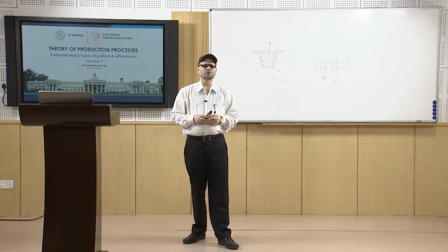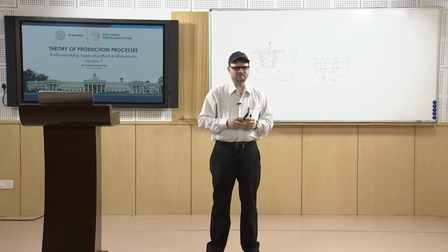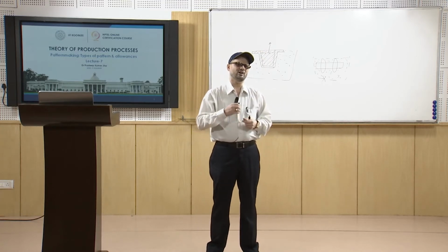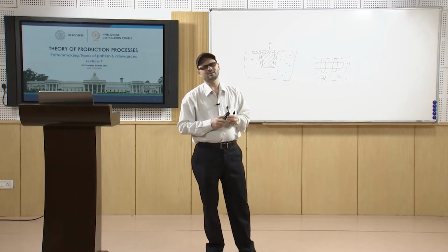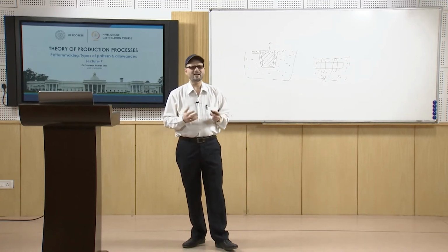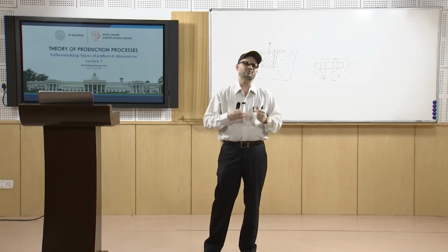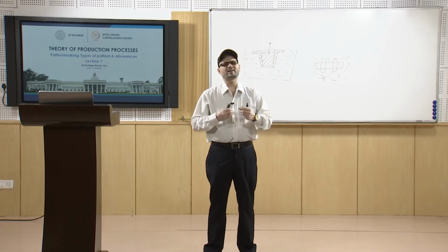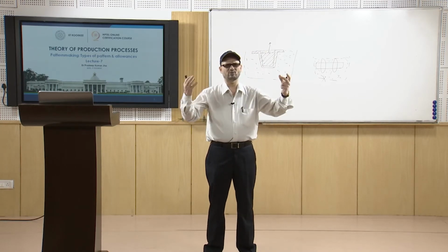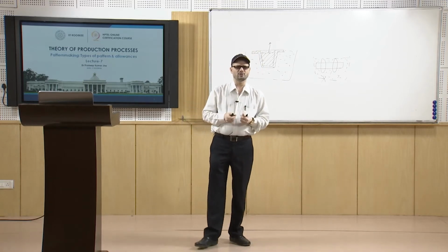Then coming to the cope and drag pattern and the match plate pattern. So far we are discussing patterns where normally we do hand molding, hand ramming, but many a times we have to go for the mechanized process. Sometimes we are going on the machine, and with the machine itself you are making the mold.